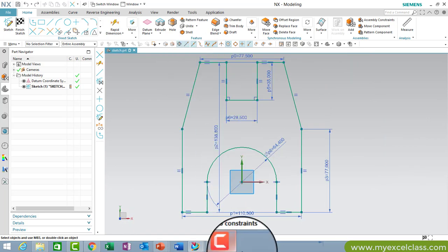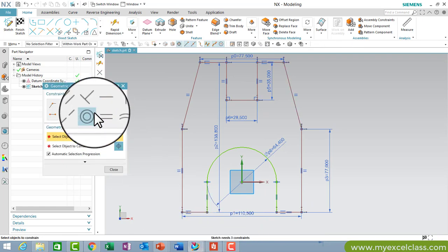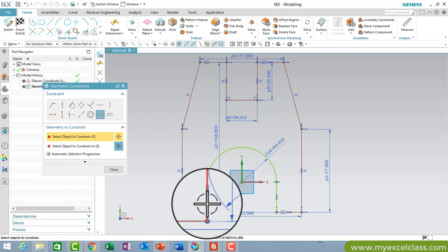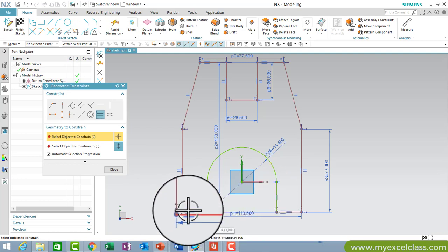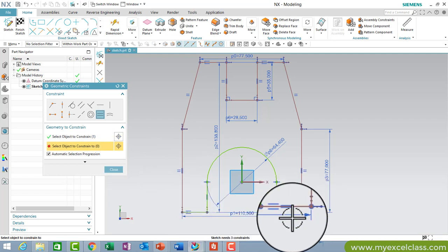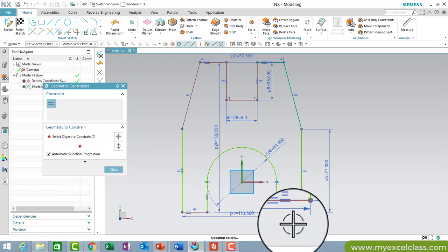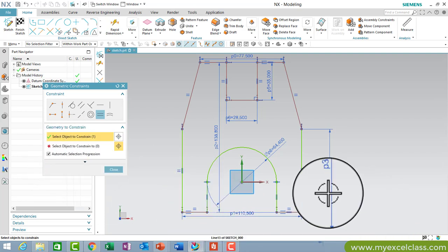So now I'm going to hit the geometric constraint, and I'm going to hit the equal length. Okay, so I'm going to try and make everything equal here. So this is a collinear symbol, so don't get confused. This is an equal symbol. So this one with this one. Okay, I made it equal. So one more constraint remaining. I'm just going to make these two equal.